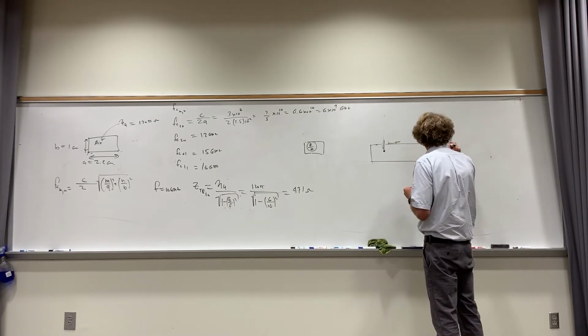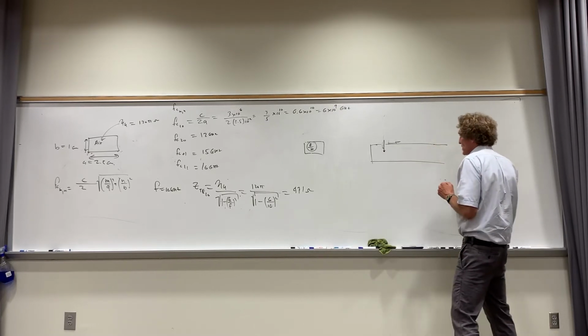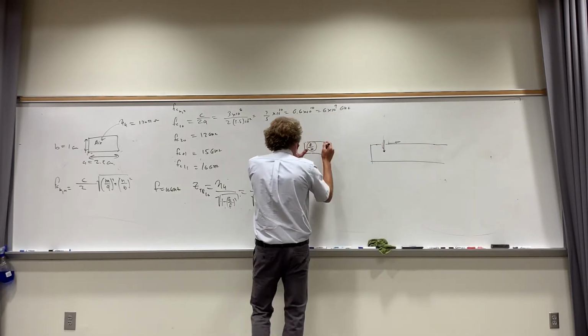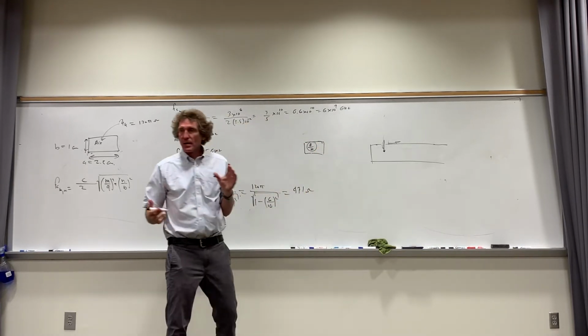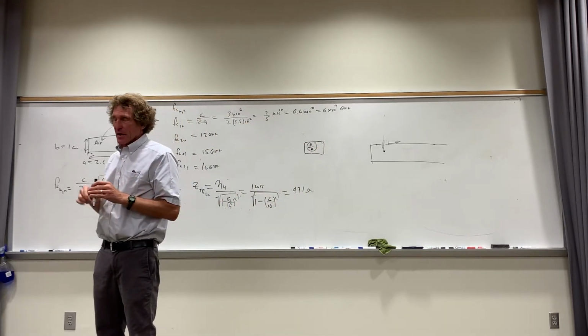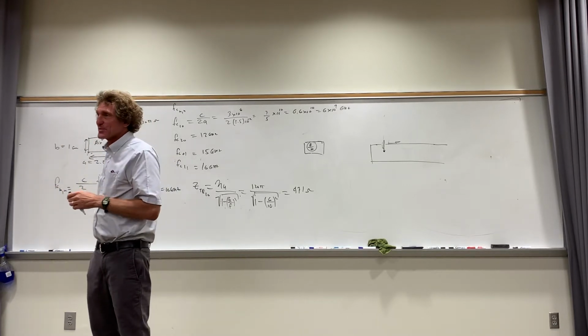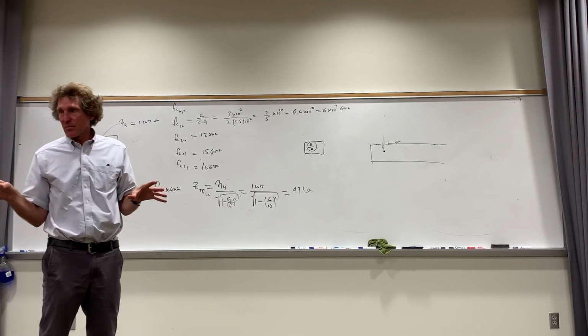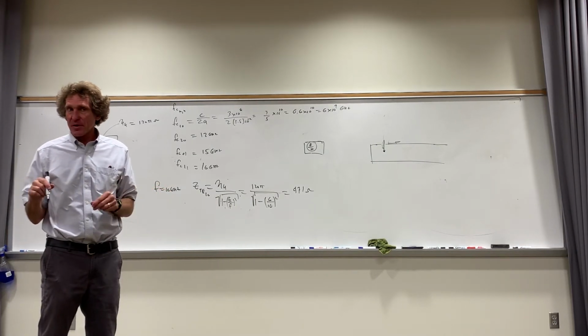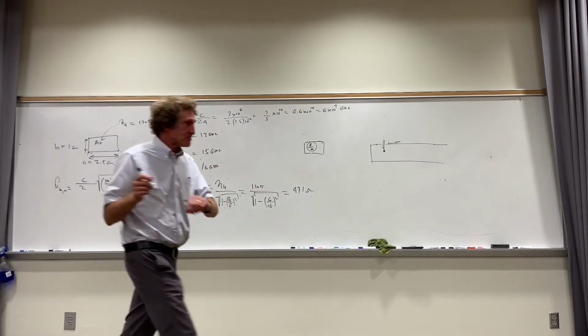A lot of times what they'll have is this. They'll have the waveguide, if you look at the square thing right there, and they'll have it just flare into a horn antenna. We have to cover antennas before I can do the impedance on that one. But the impedance will be matched so that nothing will be reflected. That's the goal of this. Okay? All right.